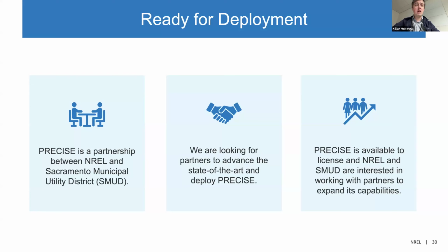The first time we tried to bring all this data together, we had an okay-ish success rate, but not good enough for prime time in terms of fully automating this. But what we were able to do is bring all this data in and use it to do a health check on the full data piece, from AMI, SCADA, and GIS, adding in all these filters for where data could be missing or erroneous to say, hey, this isn't good enough. And also track it back to the source where there might have been input errors or errors in terms of how the data was structured.